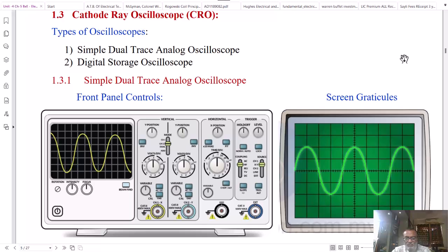Normally, this input to the oscilloscope is a voltage. Therefore, the oscilloscope is basically a device which plots the voltage versus time graph of the signal. For measurement purposes, the graphical lines are provided. Major and minor graphical lines are provided for coarse and fine measurement.